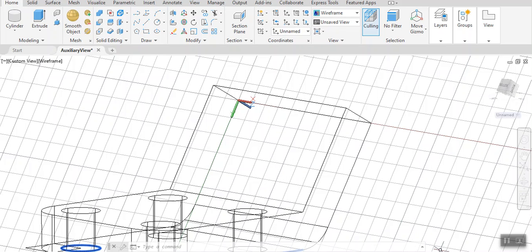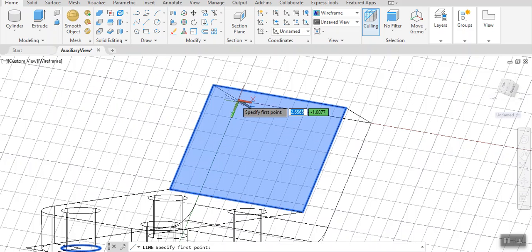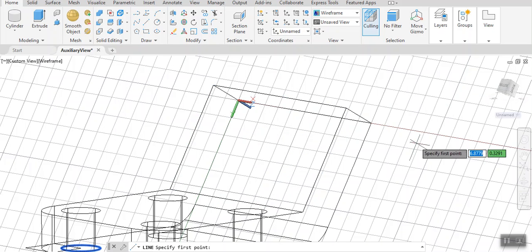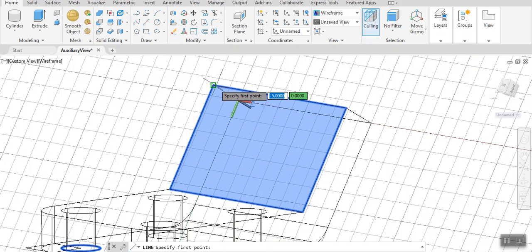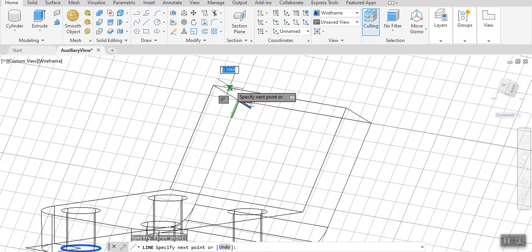Now we're talking business, because I can draw lines and I can create holes, okay, based on those reference lines. All right, so I'm going to go to the line command. How do I do that? I'm in the 3D menu. Is it there? Yeah, there is a line command here. I find it. So I'm going to move my cursor. Okay. And generate the first 1-inch line. Enter.